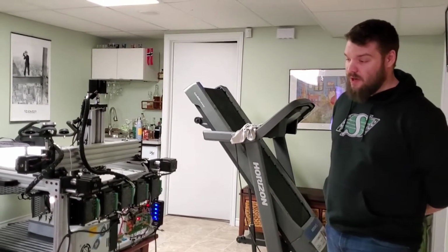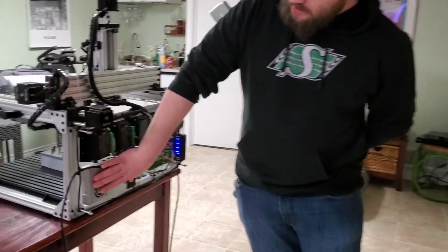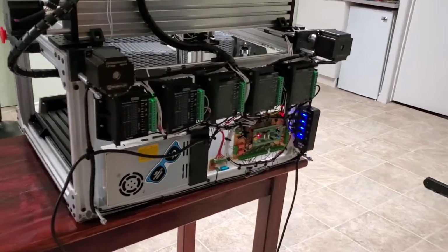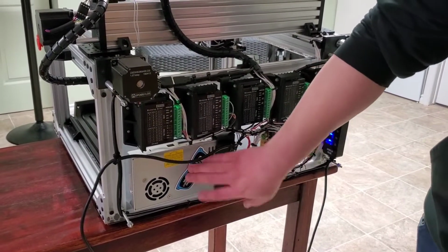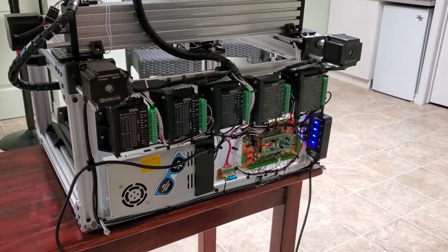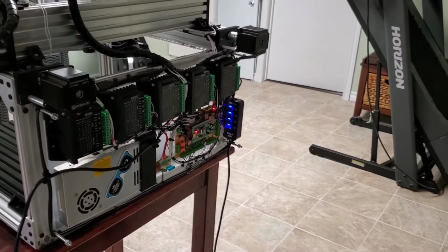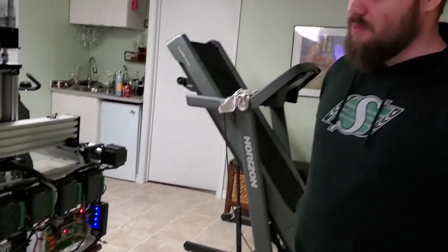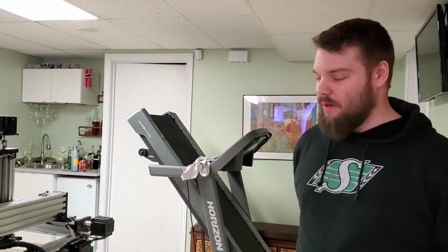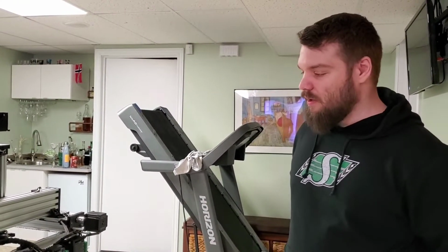So next I'll talk about our power supply subsystem. It has a couple components. Our main component is going to be this power supply here. It's running off of 120 mains. It's a 24 volt power supply rated at 14 amps, which is how much current we can supply to all of our motors. Now that's spec'd a little bit higher than we needed. Of course, when sourcing our power supplies, we found that this was just the best cost for what it was able to supply. So we didn't need quite the 14 amps, but we were close at around 12 to 13 amps. So still enough room for that.